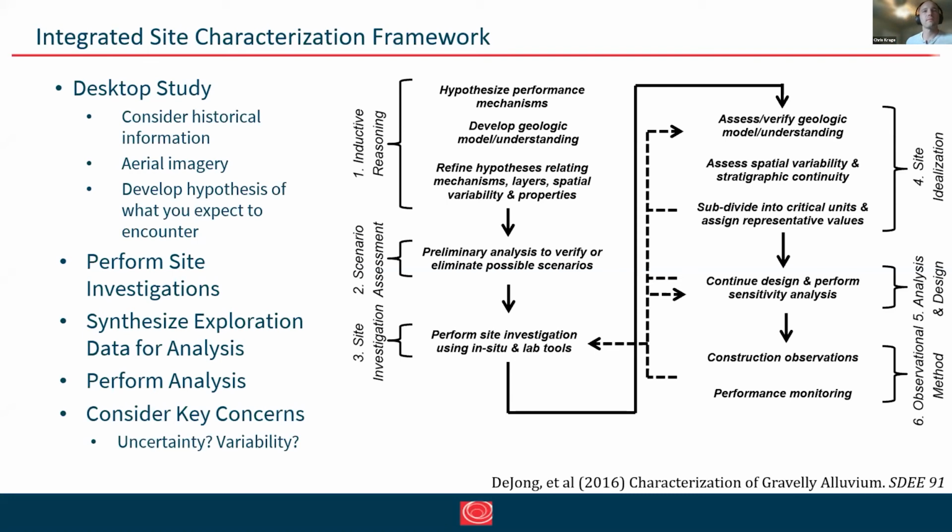But essentially, there are some key components here, and it's going to be your desktop study, which should be completed before going out, even in support of the design of the exploration program, where we gather all the available information that we can on our site and on our region, looking at historical information, aerial imagery, and coming up with our hypothesis. What do we expect to encounter? Because that will really help us with regard to selecting the appropriate tools for our site investigations.